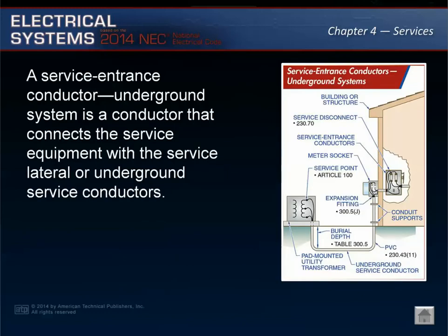A service entrance conductor, underground system, is a conductor that connects the service equipment with the service lateral or underground service conductors. The informational note following the definition of underground service entrance conductors in Article 100 points out that in some electrical service installations there may not be any service entrance conductors. In other installations, the service entrance conductors may not even enter the building. This depends on the configuration of the service and the location of the service disconnecting means.